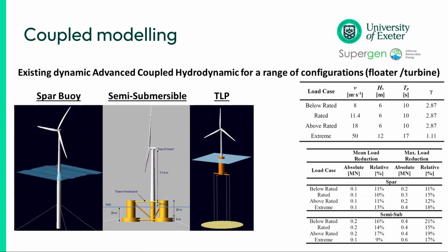Which leads me to the coupled modeling, because for floating wind, and that's a lot of the research that we do, there's a number of existing models, and some of you might well be using those for the different floating wind types, and we have a good understanding of different mooring systems and what the load cases are, and the cable then has to be designed in, and a lot of the times the cable is then added onto it. But our belief is that you actually need an integrated design between the moorings and the cable, because one relies on the other.